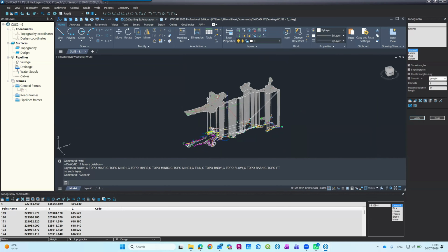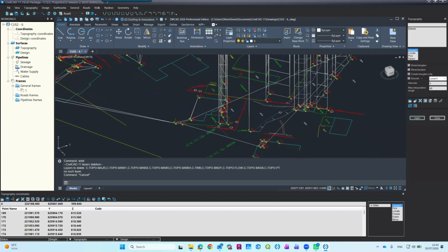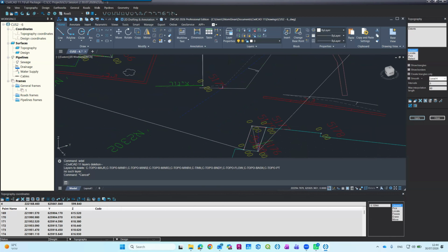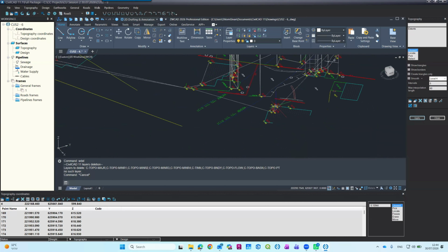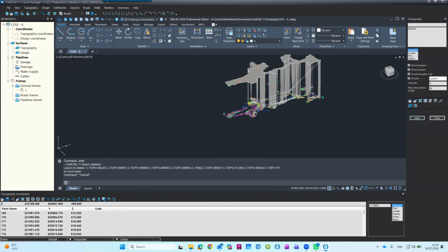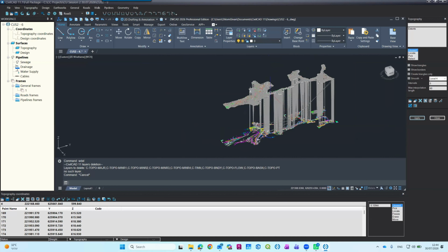That means, I'm telling you straight ahead, that some of the points which were filtered went into 0. You see this point? This is 0, 0, 0, 0. As you know, 0 is also an elevation. It's not a freeze point. So the software automatically did interpolation between this into 0, and obviously this is not a good surface.